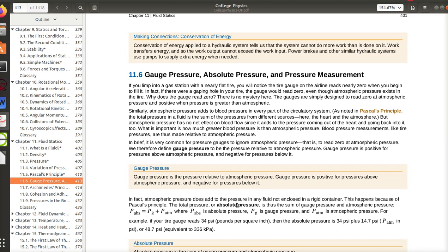So area is area, but volume is volume. But when you start talking about pressure and temperature, you have to go to an absolute scale. And if you don't go to an absolute scale, then you're introducing a false 0, and it works out for both pressure and temperature.